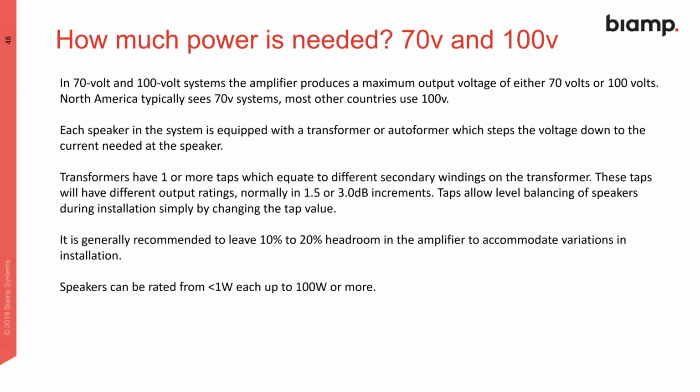So we can drive the energy to drive the magnets within the device. And those transformers at the speaker usually have one or more taps. They've got the primary winding, and then they've got the secondary windings, which resonate with the primary and give you your various step down ratings. It can be a step up or a step down transformer. You're stepping down from high voltage to low voltage.